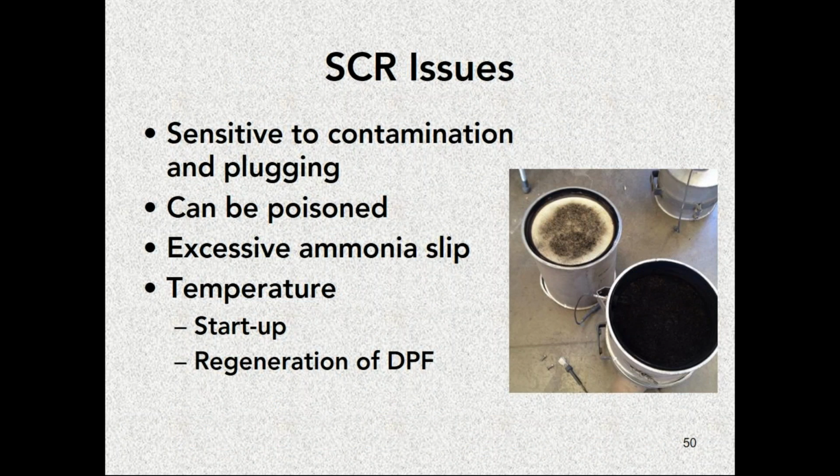There are some issues with this system that you should be aware of. It is sensitive to contamination and plugging. The SCR catalyst is easier to poison than a lot of catalysts. If the temperature is not right, the SCR systems operate in a very narrowly defined temperature zone.